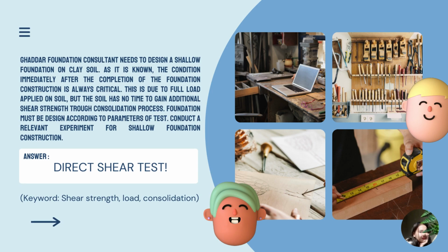So actually, the question that we have got is regarding shear strength, load, and consolidation. A geotechnical foundation consultant needs to design a shallow foundation on clay soil. As it is known, the condition immediately after the completion of the foundation construction is always critical. This is due to full load applied on soil, but the soil has no time to gain additional shear strength through the consolidation process. Therefore, we need to conduct a relevant experiment for shallow foundation construction, and the foundation must be designed according to the parameters that we got during the laboratory test.